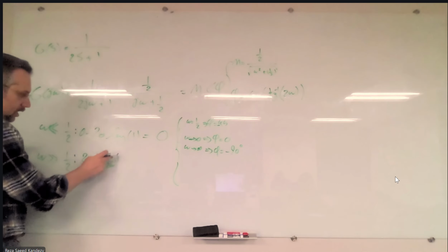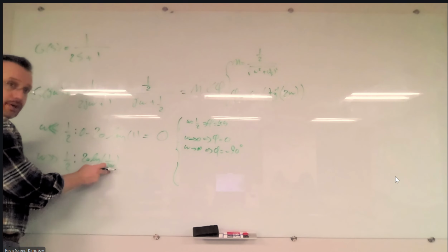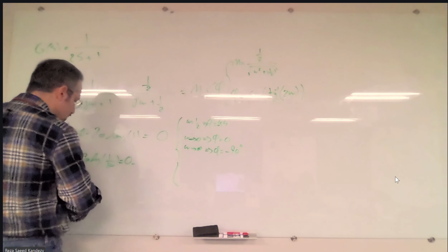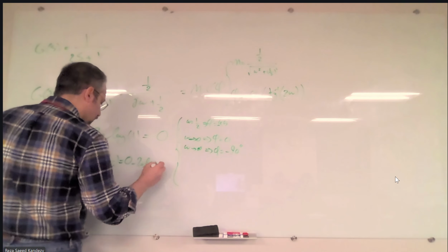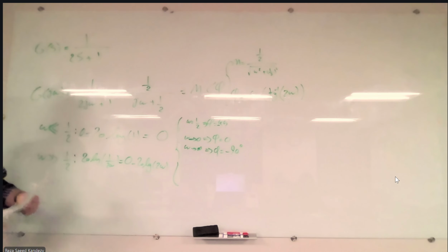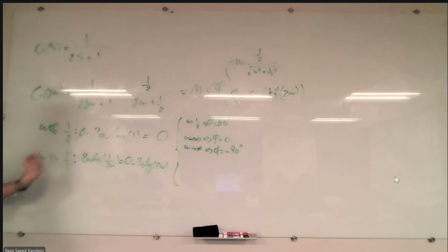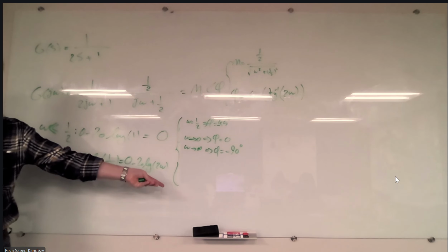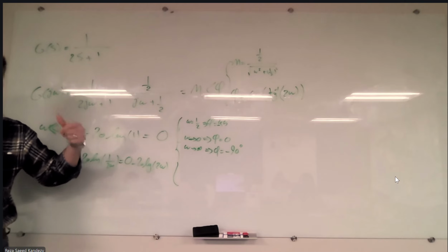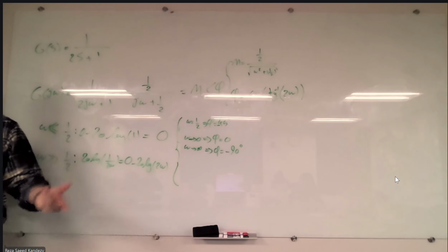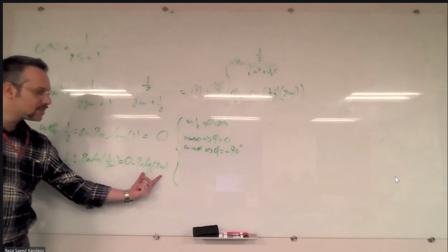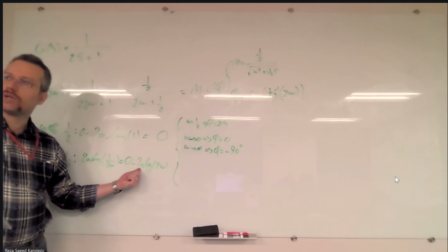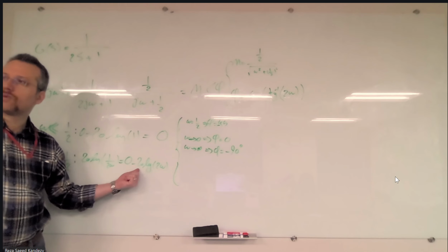Now this one, we can split the numerator and denominator. It is going to be 20 log of 1, which is 0, minus 20 log of 2 omega. Now, you can extract the 2 out of that, so it's going to be simply 20 log of 2 plus 20 log of omega. Are we good? So we can extract that, but you don't need to do that actually, because eventually we are going to see a line with a slope of minus 20. Is that clear what we're talking about?